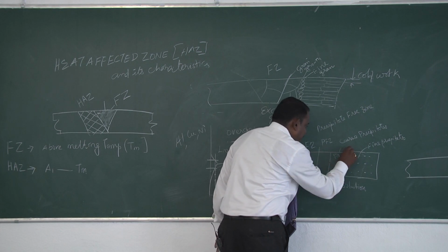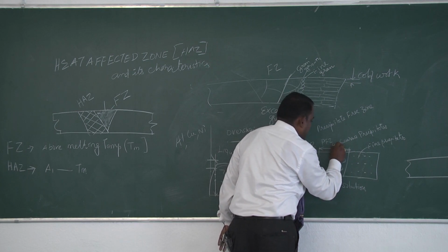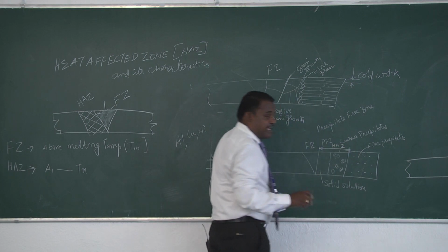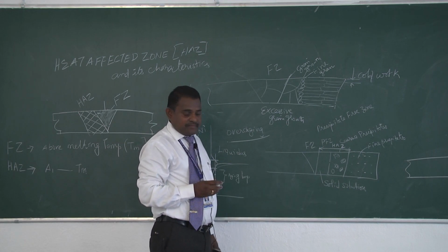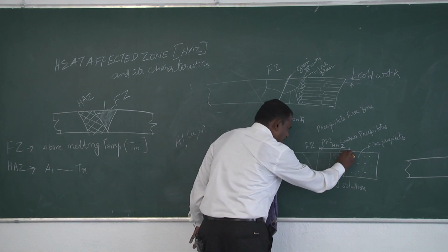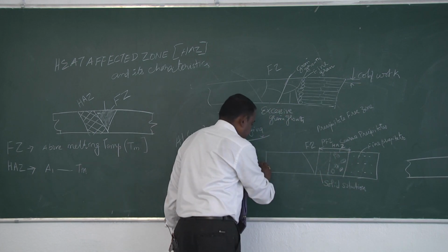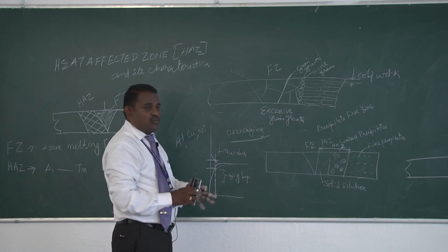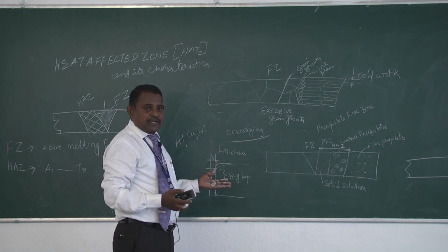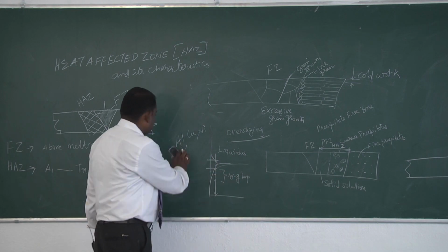So the combination of these two is the heat affected zone of the material that is designed for the precipitate strengthening mechanism. This will also deteriorate the properties of the weld joint. Until now we have discussed four different kinds of materials with respect to their strengthening mechanisms and their various morphologies.